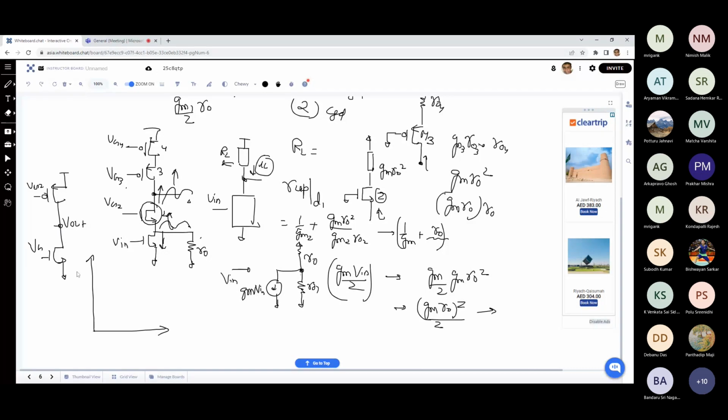And the gain is also high, right? So high gain means what? In your transfer characteristics, this curve is also very steep. If this curve is steep, that means if you are trying to bias it over here, you have a very small window basically. And it's very difficult to ensure that automatically, by just sizing these devices or fixing the VG1, VG2, you will end up in this narrow range. It's very difficult.